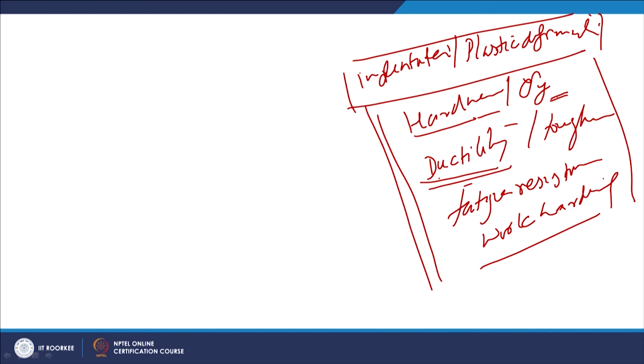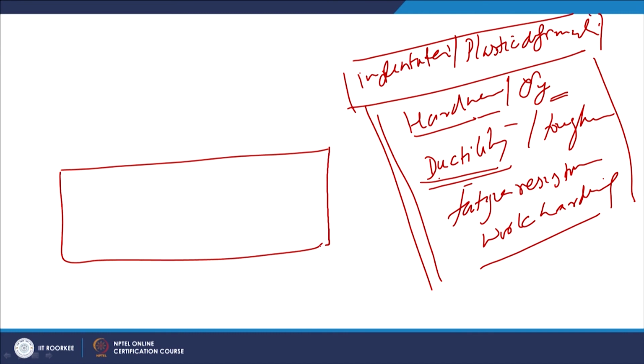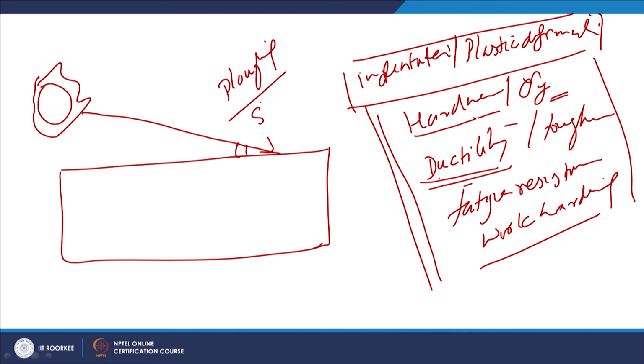So, if we see what are the mechanisms which play an important role in governing the removal of the material from the functional surfaces. Say if a particle having sharp edges like this impinges on the surface of the workpiece at a low angle, it will cause ploughing, and sometimes the sharp edges cause shearing to remove the material by cutting action.